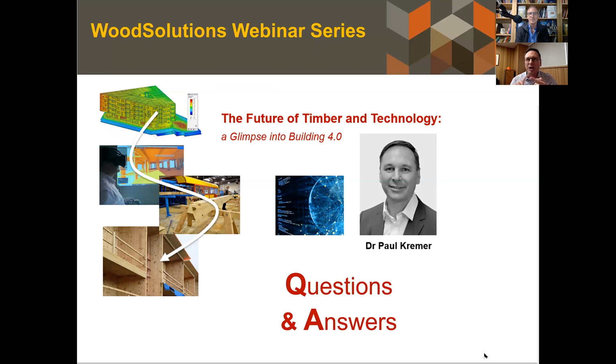So the Australian standards don't necessarily call for it, but people like XLAM and others do a treated product in the wet areas, and that's put in place as a preventative system. In New Zealand, it's actually a standard treatment for all panels and the preventative system for bathroom and wet areas to mitigate their leaky building syndrome. So happy to have a chat offline for either of those if you want.